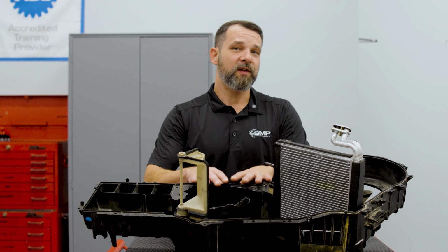We have our heater core that will be sitting here. We have our evaporator core. And of course, if we want heat, we can move our blend door and pass it across our heater core. If we want air, we can pass it across our evaporator core. However, over time, especially if these have been pulled in and out, as maybe it's been replaced, any damage, and you can see we have some here on this particular one, any damage to the seals or the sealing properties of both the evaporator core, the heater core, and even the blend doors, any sealing degradation is going to cause us not to get the climates that we're asking for.